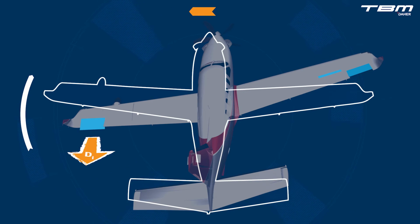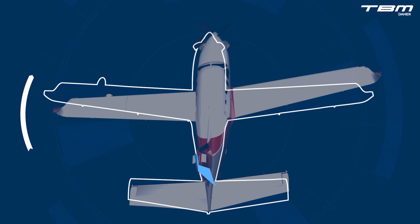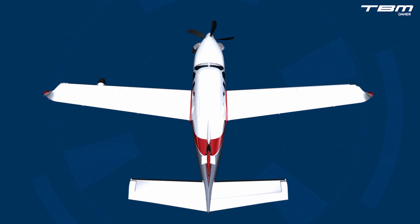The TBM's advanced aerodynamic design incorporates spoilerons, which assist with roll control and mitigate adverse yaw. Despite this aerodynamic advantage, one should manage propellers' rolling and yawing tendencies by giving the rudder priority for roll control when maneuvering in the low-speed regime.